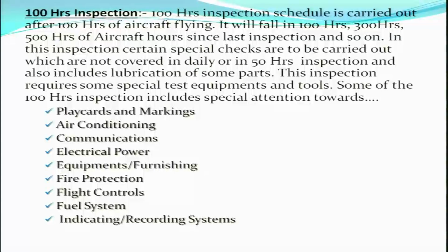Some of the 100 hours inspection includes special attention towards placards and markings, a very important thing. There are various placards and markings all over the aircraft, so we need to check whether all the placards and markings are there on the aircraft as is specified by the manufacturer.